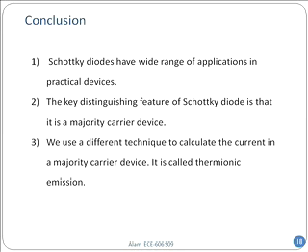And you realize that because I had this heterojunction, not because it's metal semiconductor, but because I had a discontinuity in the conduction band, I had to use thermionic emission. Anytime, next time you see a discontinuity, regardless of whether it's a metal semiconductor or two semiconductors, germanium and silicon, with a discontinuity in between near the junction, use thermionic emission current. That's how you should calculate it.